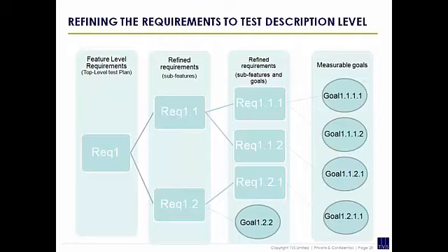So what we would do is map these down maybe to a functional coverage point, or an assertion, or a proof, within your constrained random. Remember I said that the randomness is all controlled by seed. And it's important that you have the seed because you need repeatability. Okay? So your constrained random environment, although it looks random, is actually randomized purely by one seed number, which is fed to the test bench. And if you give the same seed number, the test bench will do exactly the same thing. So it's called maybe pseudo-random because it's all constrained by this seed. And that seed is randomly generated. So if you feed the same seed to your random test bench, it does exactly the same thing.